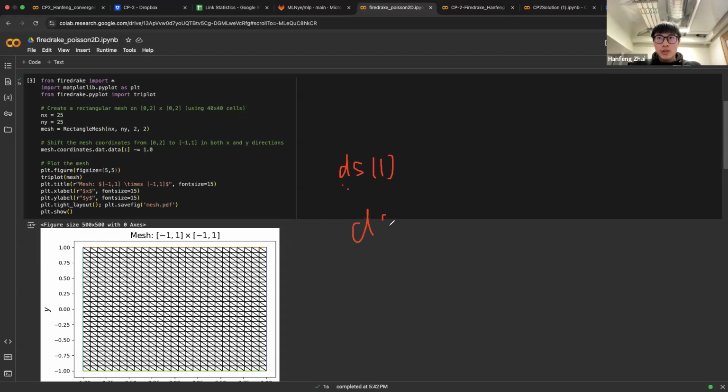1 and physical group 2, etc., or any number. And you have to think about how to impose your Neumann boundary condition according to the specific physical group of the domain. Because here I didn't define a physical group. You can imagine if you define a physical group accordingly, where you can have a hole in your domain, then you can recall exactly what boundary you are referring to and put that into your linear functional, as part of the force vector, and you can impose your Neumann boundary condition.